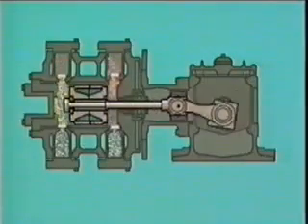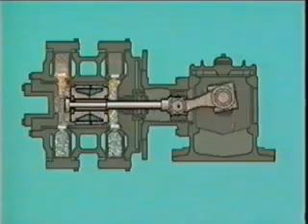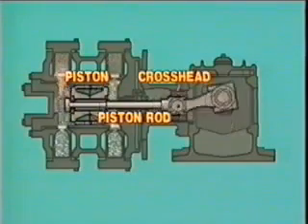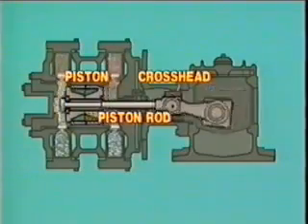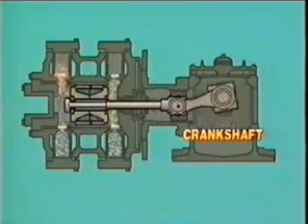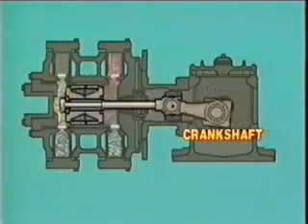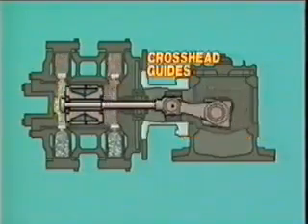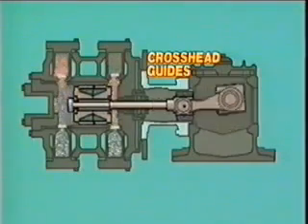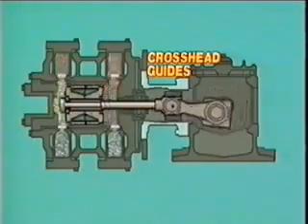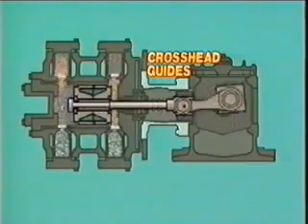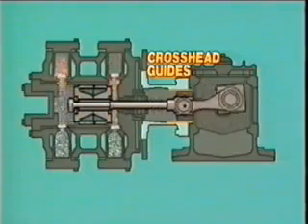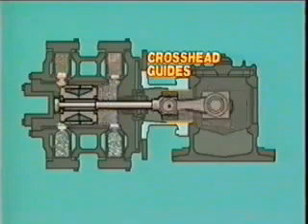Within the compressor, there are two types of rods, piston and connecting. A piston rod joins the piston to the crosshead. The crosshead converts the rotary motion of the crankshaft into the back and forth motion of the piston. The crosshead must be held in very close tolerance to the crosshead guides to ensure horizontal, level motion of the piston. Slippers, shoes, and shims are used to keep this close tolerance. Here again, lubrication is important, and crosshead slippers are lubricated from the crankcase or through ports.